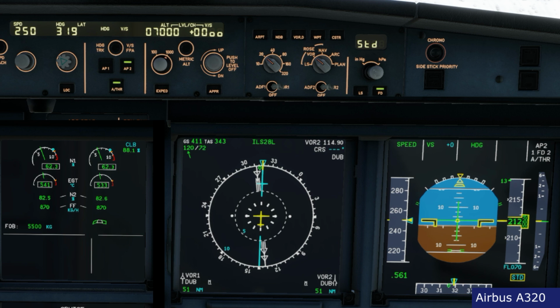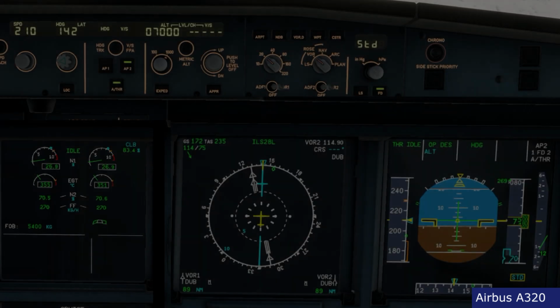And of course, now that I realize what the problem is, that I changed the altitude and I need to descend, if I pull back toward me again, I activate the open descent, so the system detects that the selected altitude is lower than our current altitude, and what happens is that we start descending.